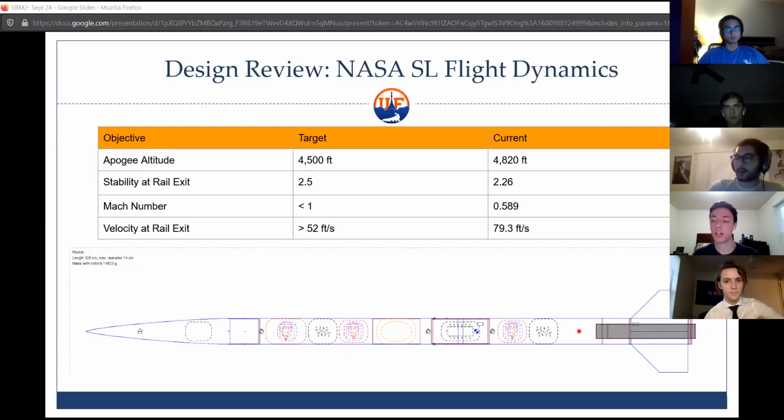Quick question, Matthew. Yeah, go for it. What diameter is the rocket, and is there ample space for the payload? It's a 5.5 inch diameter rocket. You can see the payload in the model. It's one of the boxes, and inside there are two yellow or orange ovals, one inside the other, that represent the payload. As of the current estimate I had for the payload, it would fit within that diameter of rocket. We were initially going to use a smaller diameter, so I went to 5.5 inch to give the payload some more room. As of right now it should fit, but we can continue to reevaluate that if anything changes.